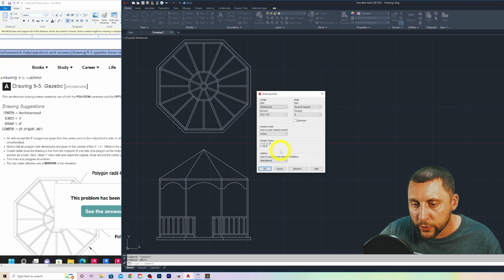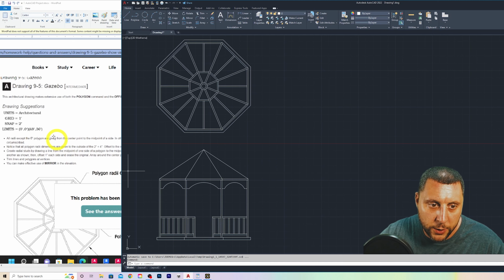for feet and the quotation sign for inches. Or if you leave the quotation off and just do like 5 enter, that would also be 5 inches. Okay. So 5 apostrophe is 5 feet, 5 enter is just 5 inches, or 5 quotation is 5 inches as well. All right. So go ahead and hit OK on that.